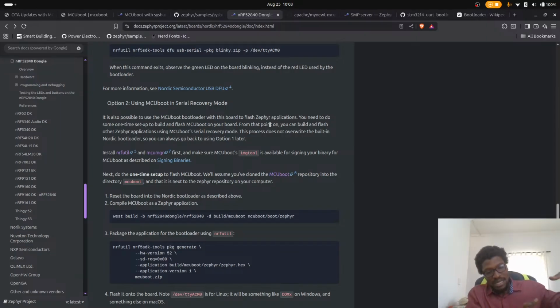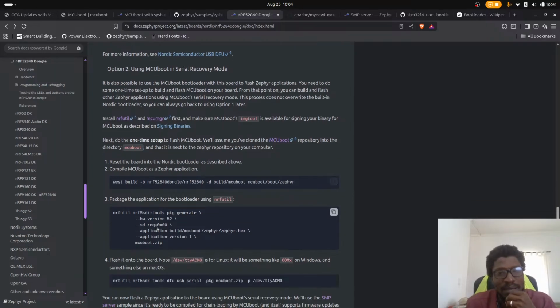Basically, you flash MCUboot at the factory, and then you flash version 1 of your software at the factory, and then the device goes to the edge. Okay, and then you get an update of your software, you send the update to the device by some over-the-air mechanism, and you don't have to rewrite your bootloader that was on top. That was the base. What you have to do is rewrite just the resident application.